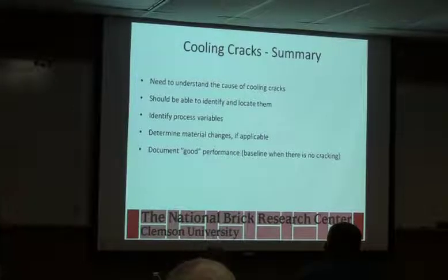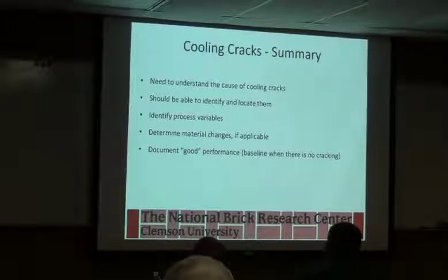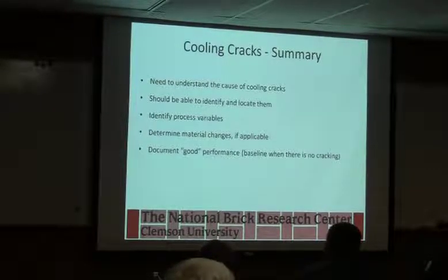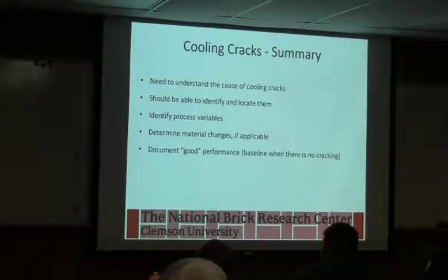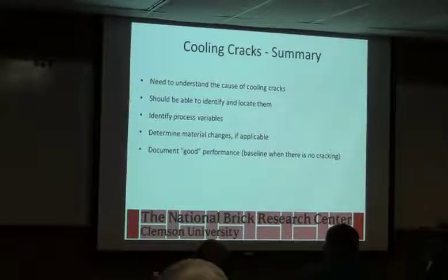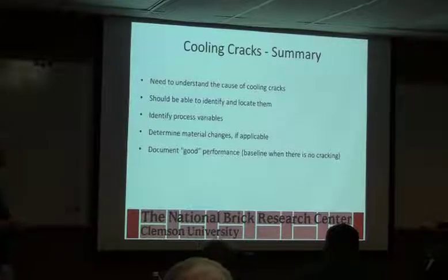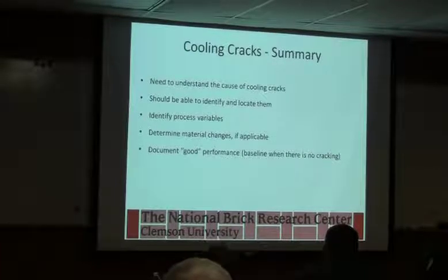Need to understand the cause of cooling cracks. You should be able to identify and locate them. Identify the process variables, again, understanding your process when it's working well. And then when you do have an issue, go back and compare what changed in the process. Determine material changes if applicable. Document good performance as a baseline.